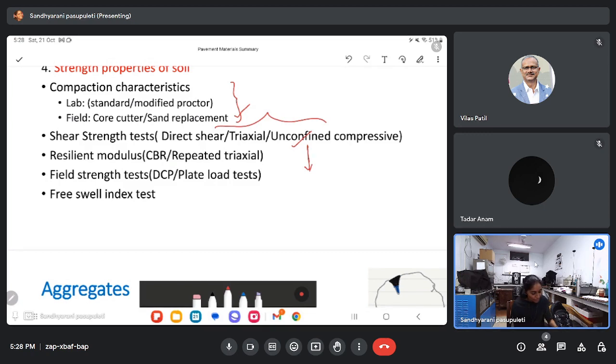When a vertical stress is applied, a shear plane or weak plane will form through which the material is going to fail. If we have confinement from the surroundings, the material will not fail immediately. If there is no confinement, it will fail immediately. So in the unconfined compressive strength test, we use zero confinement. In the triaxial test, we use more confinement.